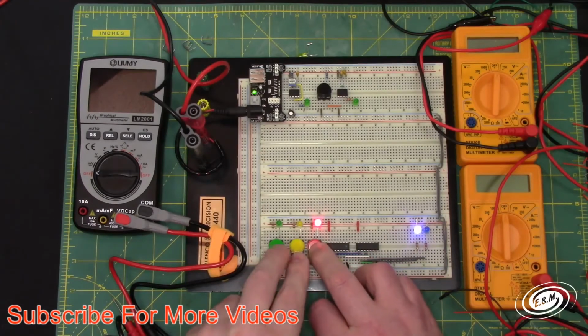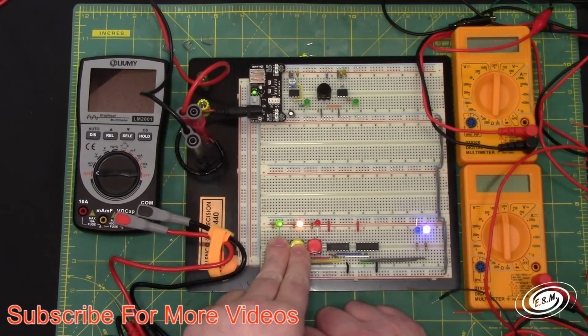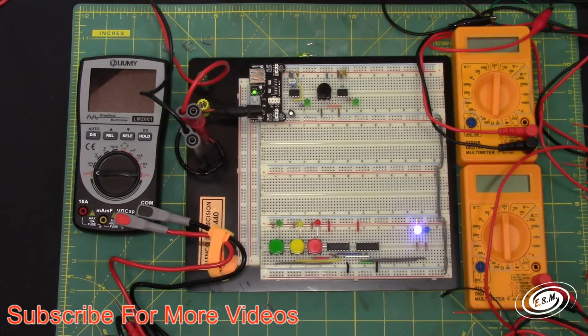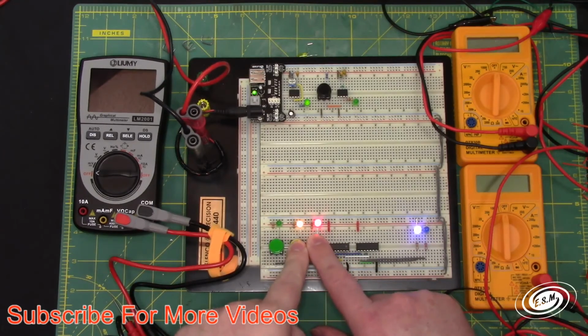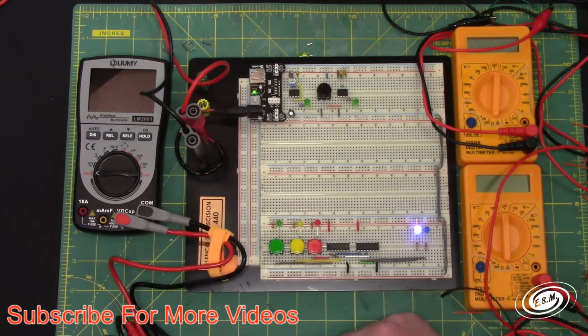And if you press both of them, it still errors out. But if you press both of them when the enable's not enabled, it works out. So if you want to clock data this way with an enable, you can make sure you have your write one done before you push the enable. So you press your set, and then you press the enable, you press your reset, and then pop the enable, set, pop the enable. So you can have your S or R high, and then have a pulse come in and set it, and then everything can go low, and then you could set up for another input.